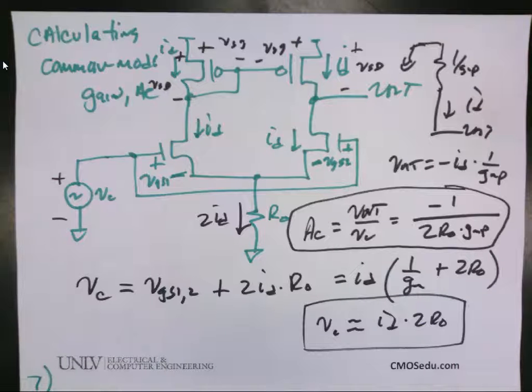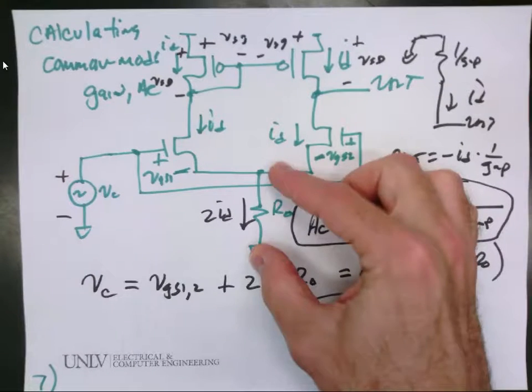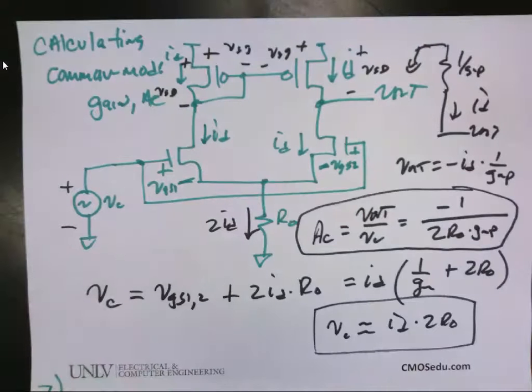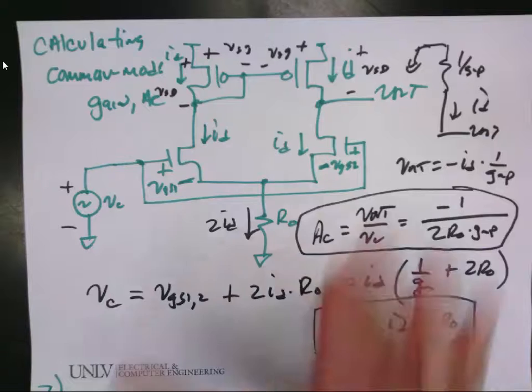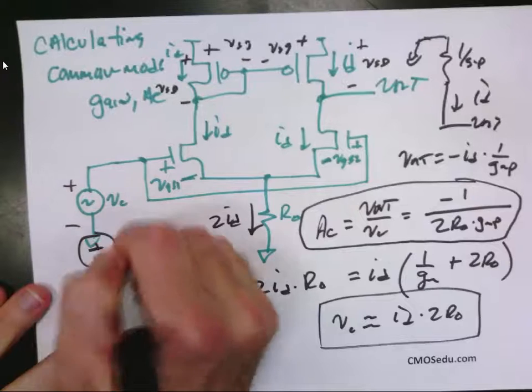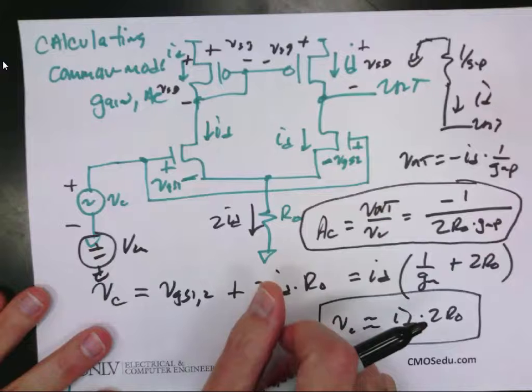Nope. When you're designing op amps, you assume that everything's operating in saturation. If it's not, then all these calculations in the small signal approximation don't work. So remember when I started drawing this, I said I'm not going to draw the DC bias. I'm going to assume it's replaced with its small signal, so I'm only going to talk about AC gains. Does that make sense? So I assumed that I've got a DC common mode. We have to have some common mode voltage that biases everything on.